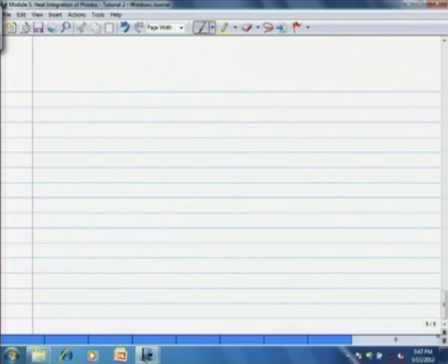So, now we start developing the heat exchanger network. Above pinch, 520 degrees hot stream temperature, 500 degrees cold stream temperature. Cp values I am listing here separately.